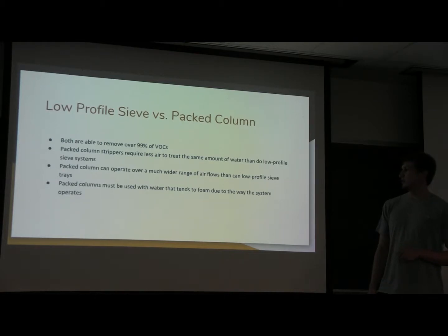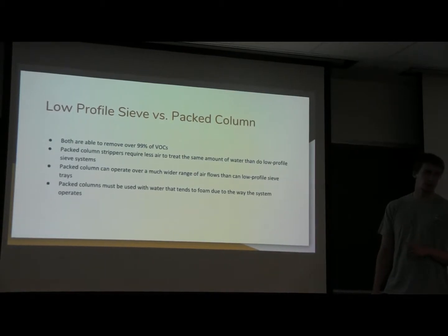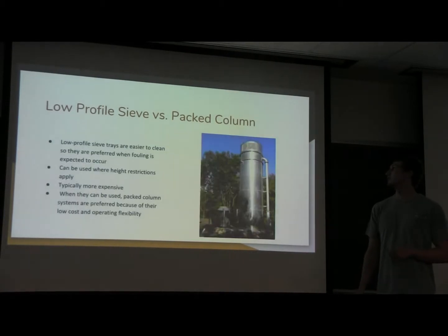However, one disadvantage of the packed column is it's very susceptible to fouling due to the packing materials and the tighter spaces. So you need a water that's going to be able to flow easily and not foul very much, because they're also very difficult to clean once fouling occurs.